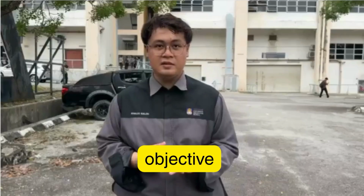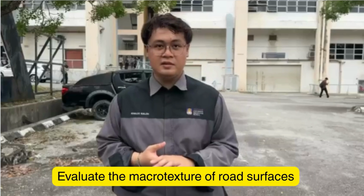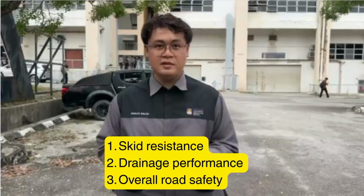For the surface texture test, or the sand patch test, the objective is to determine the surface texture depth of a pavement by measuring the average depth of sand spread over the surface. This test is used to evaluate the macro texture of road surfaces, which influences skid resistance, drainage performance, and overall road safety, especially under wet conditions.